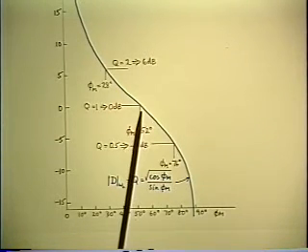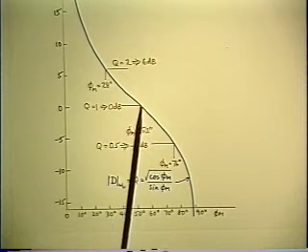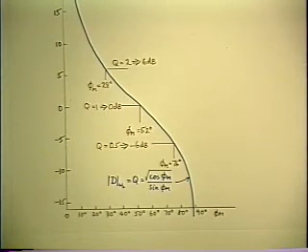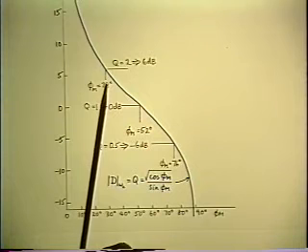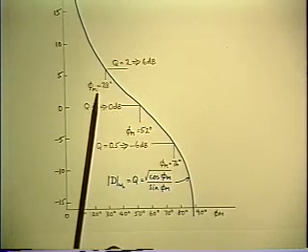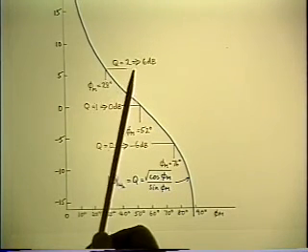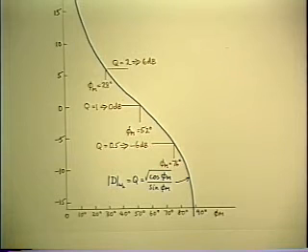If you go in the other direction, when I asked the question at the very beginning of this section, how much phase margin do you think is necessary, I was pleased to hear no one said anything as low as 30 degrees. Because look what happens. 28 degrees gives you a Q factor of 2. 6 dB of peaking in your closed loop response.